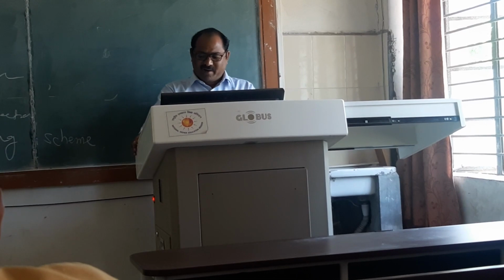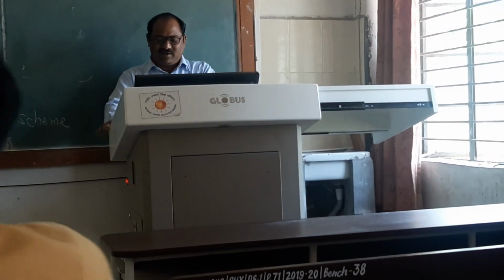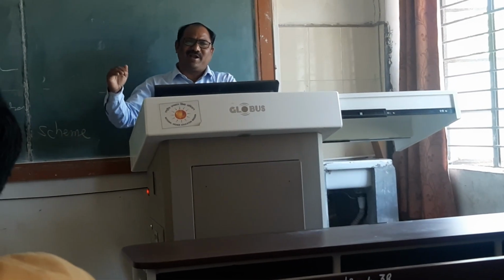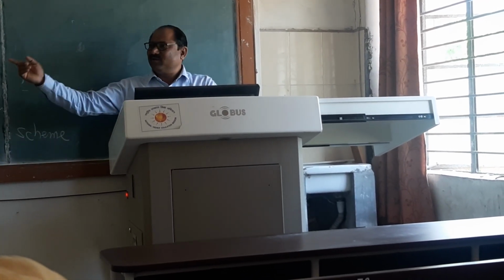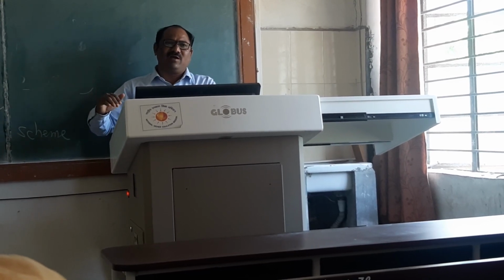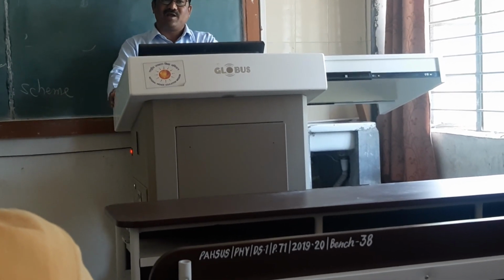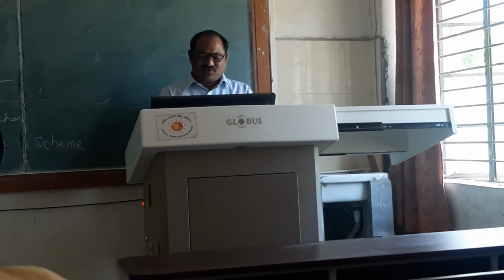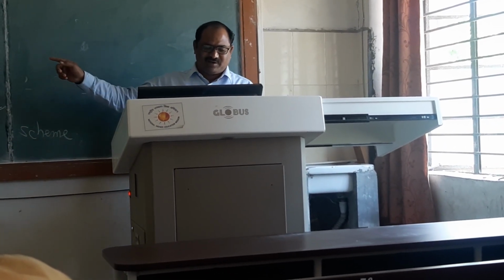First you have to load the lower byte data, then load the higher order data. So this is the write sequence. The first step is to write a control word into the control register, the data available on the data bus. Next, load the lower byte on the data bus. Then load the higher byte on the data bus for the counter. Then the counting starts. So these are the write operations.